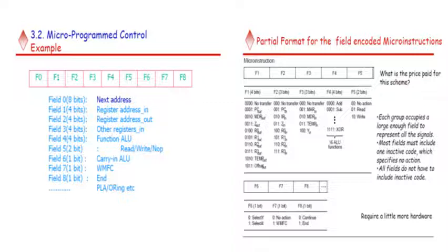When the microinstruction sequence is controlled by a microprogram counter, the end signal is used to reset the microprogram counter to point to the starting address of the microinstruction that fetches the next machine instruction to be executed. In our example, this starting address is 000 to the base 8.